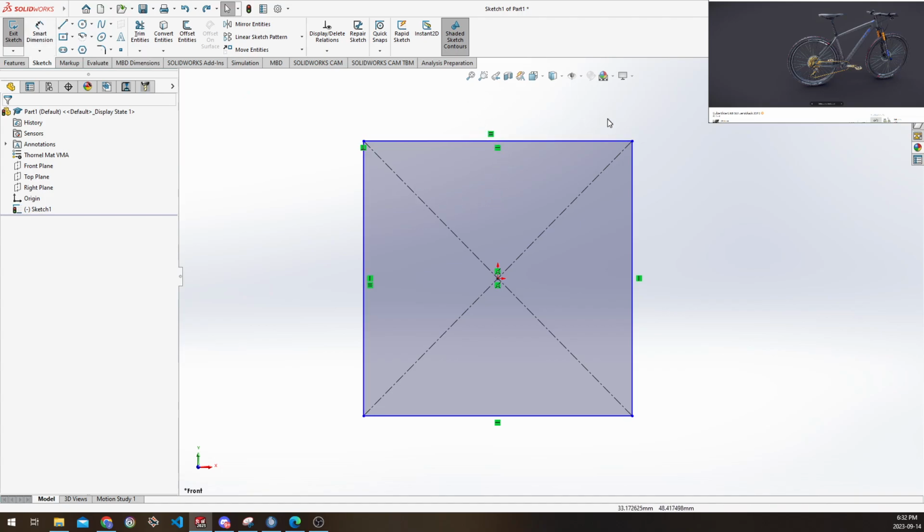As soon as you start worrying about scale, there are a few things you need to take into account. When you're making your first part, in the bottom right corner here, you'll be asked which dimensional scale, which standard units, you want to use. Our team, on TMAV, we always use millimeters, grams, seconds. The reason for this is the vast majority of the parts that we manufacture on this team are designed for metric screws, metric fasteners, metric parts, and all that stuff. They typically are significantly less than the scale of a meter.